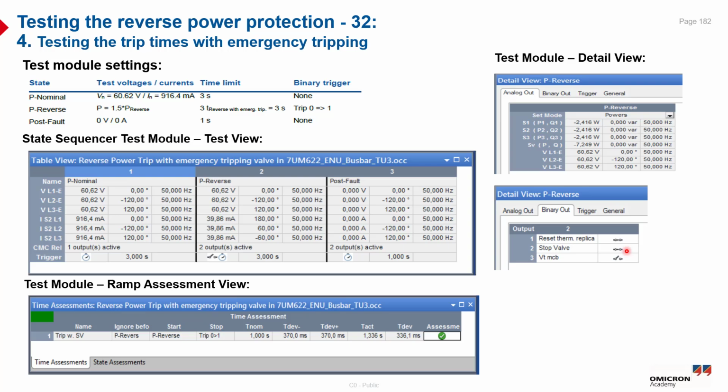Because, as we explained, the reverse power protection 32 can be seen as a pure turbine protection. So it prevents the turbine from being driven by the generator working as a motor if the steam supply is interrupted while the generator is still connected to the network. Hence the turbine tends to be overheated due to the missing steam. The reverse power protection must trip the circuit breaker considering that the valve is still closed.